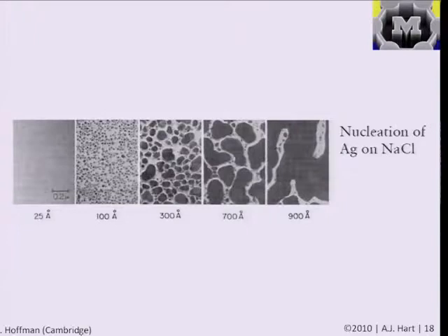And you can see with time, as more atoms hit the substrate, you end up depositing into larger clusters, and the clusters can also lose atoms to one another based on their own energetic stability and their own size, and you eventually get a film that is more or less continuous. And with time, you would evolve that grain structure in the film that would then be going from the size regime we're interested in to the size regime of continuous films. And I'm just showing you this not to bring the discussion of bigger thin film growth into our material, but to try to bridge the gap between what was done before and what's being done now by understanding the kinetics of how these structures evolve.